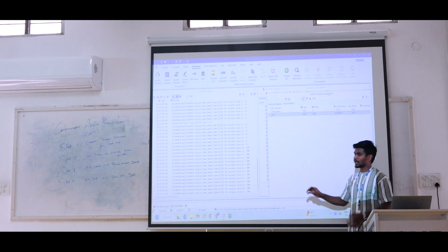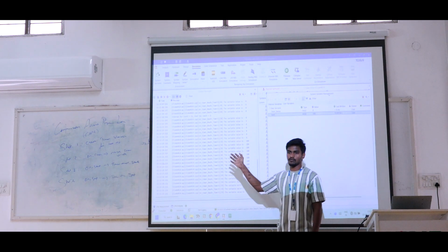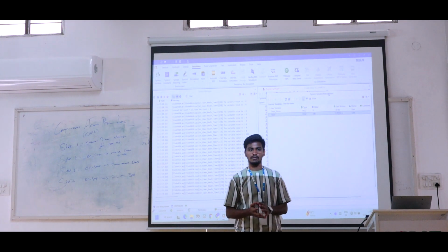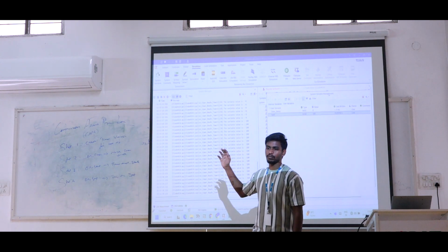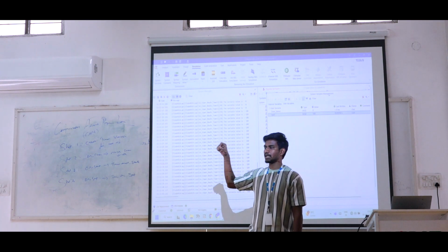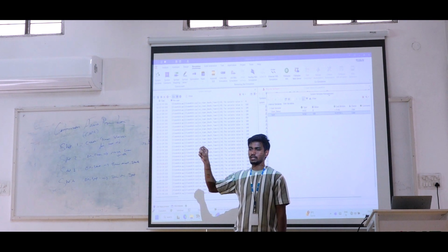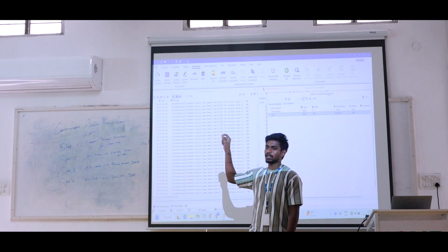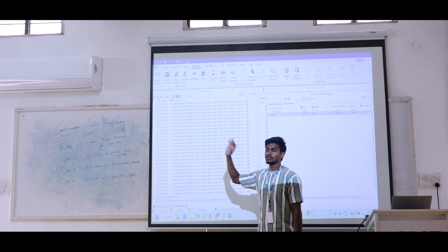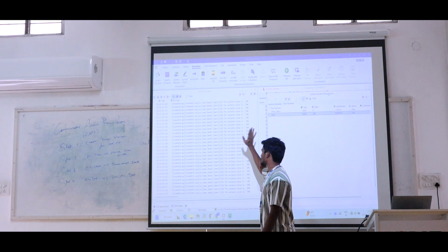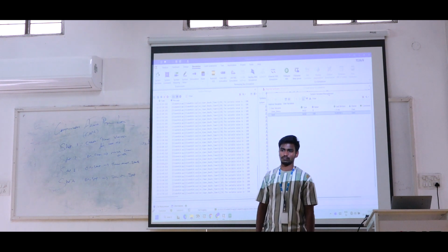If you have a background script, we have CAPL scripting. For example, we are using a condition for the remote keyless entry. The CAPL scripting is running, we are setting the timer, so whenever you receive the ID number 128, and the first bit log value is 1, the indicator turns on automatically. It means the script is running in the background, so whenever the value passes, the indication is automatically turned on.